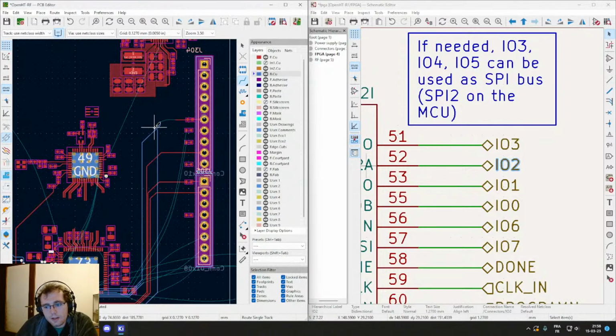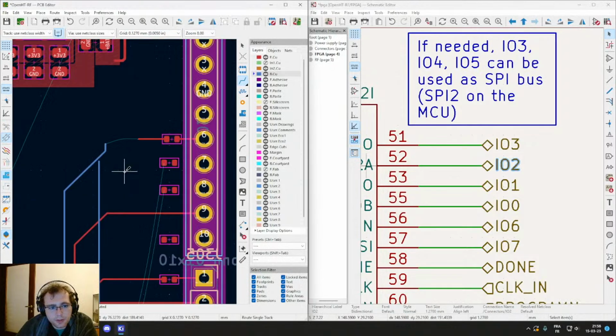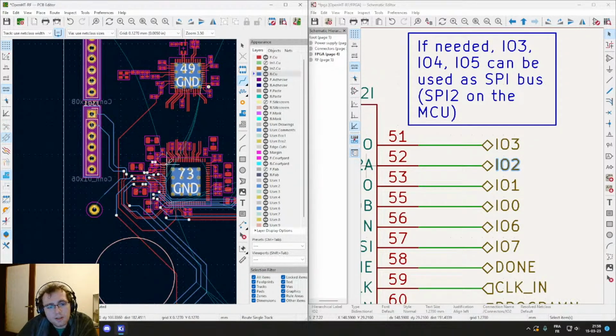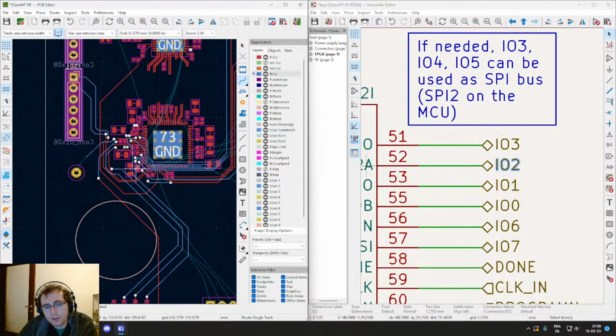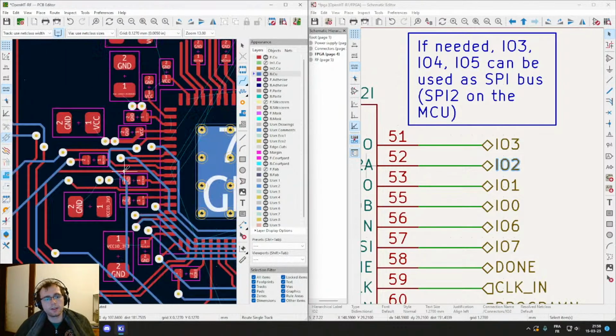So for the SPI bus, as it's gonna be a few megahertz for the clock, if you route this track over a split in the ground plane, it's gonna generate a lot of electromagnetic noise, which you want to avoid. So by routing this on top of the ground plane, then you are not gonna have any problem because the return path is just below the track on the ground plane. It's good. But yes, you can also do vertical and perpendicular on independent layers if you want it.